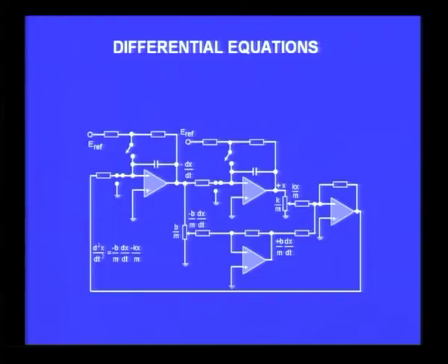When I do a solution, you find the solution mathematically, analytically. I will get the solution after performing certain mathematical manipulations, and if I want to change some of the variables or the coefficients, then I have to almost start all over again and obtain the solution once more. Here, all that I have to do is modify some of the voltages or the coefficients b by m or k by m factors, which is basically done by using potential dividers.